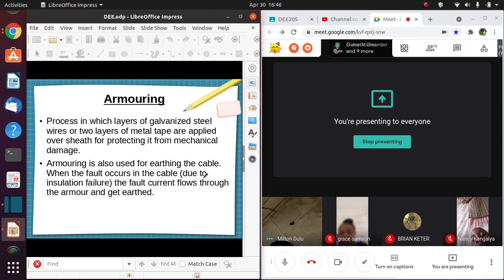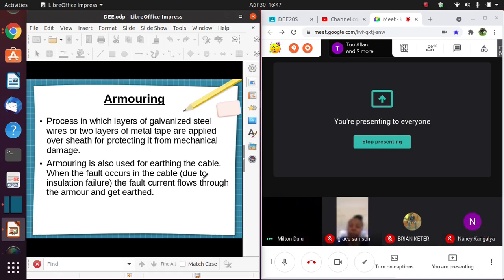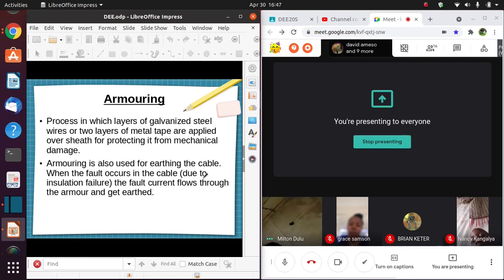Now armor, in some cables, kama there's a cable known as a mineral insulated cable, kuna conductor which transmits the live current. We have an insulation which in this case is not rubber or the like, it is iron oxide, it is a mineral. And then on top of that there is an armor, ni metallic in nature, hakuna insulation, ni armor. So this armor acts as a neutral, is the return wire. So the armors can be used as neutral connections.